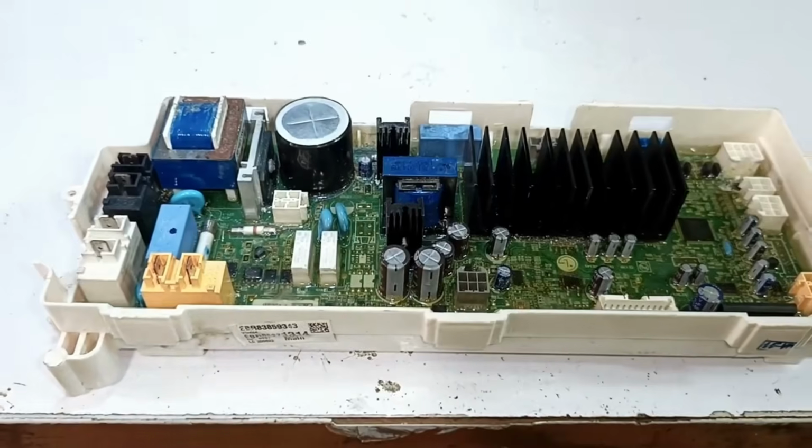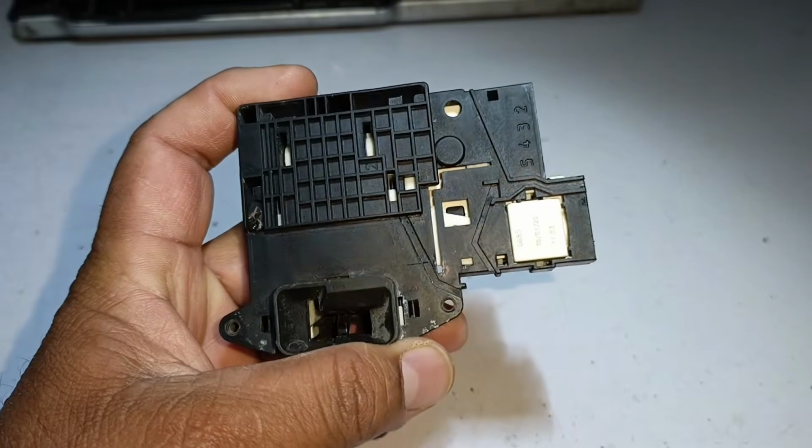If the error keeps appearing even after properly closing the door and resetting the machine 1, 2, or even 3 times, then it means this is a permanent fault. In that case, you need to check 2 main parts of the machine: the PCB control board and the door lock assembly. Most of the time the problem is in the door lock, although it can also occur in the PCB, but that is less common. The door lock usually gets damaged more frequently.